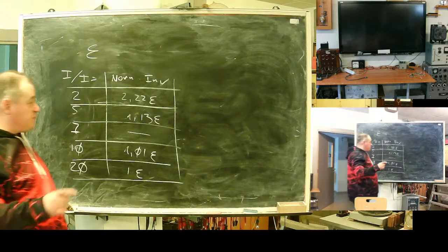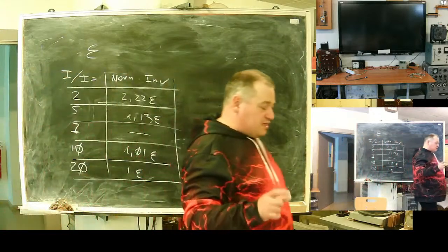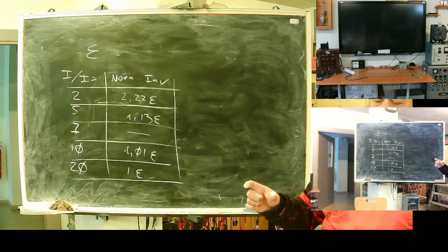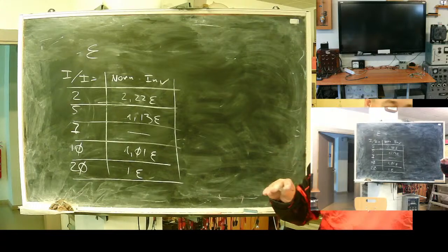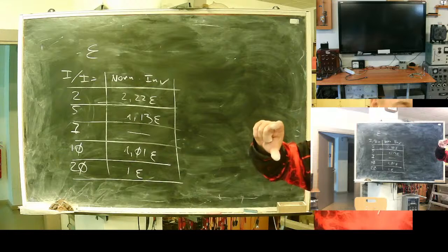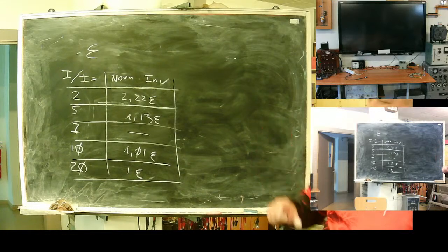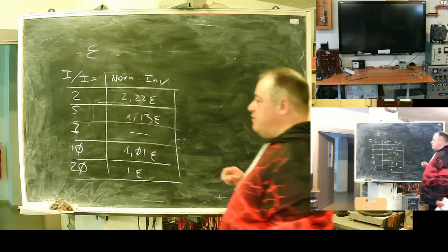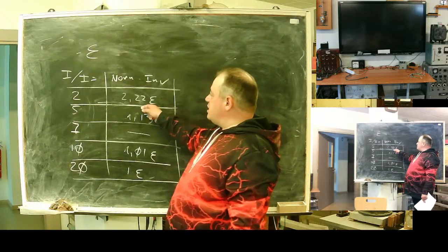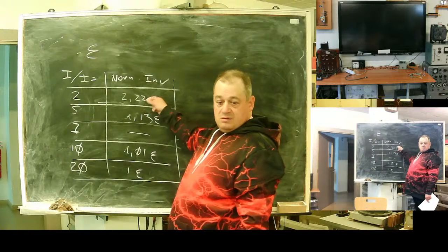If you coordinate with a fuse, remember that the tolerance of a fuse is 20%. The tolerance of an ordinary circuit breaker is also somewhere around 12%. So the safety margin should be 20%, not 10. If you coordinate relays on small currents, the tolerance margin is more than double.